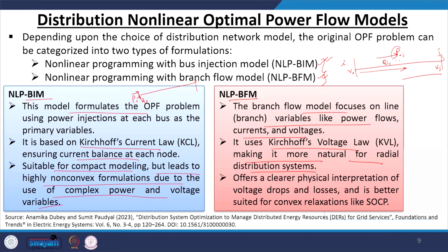So, if you deal with this power flow, then you can say in which direction your voltage reduction is there. So, it is very good to validate the problem. That means, if you see that power is flowing from Vi to Vj, or i to j, then obviously your Vi is greater than Vj, that is the physics. So, that is very easy to validate the solution,